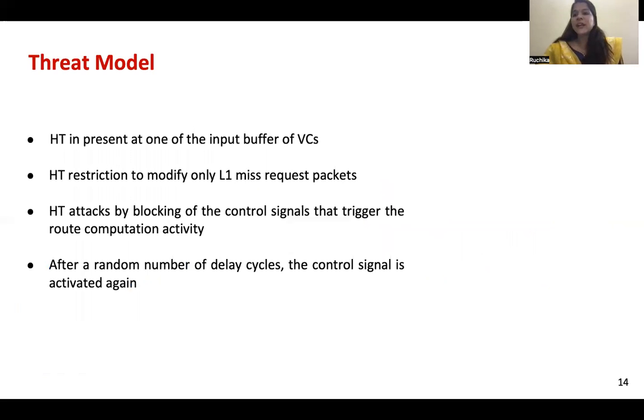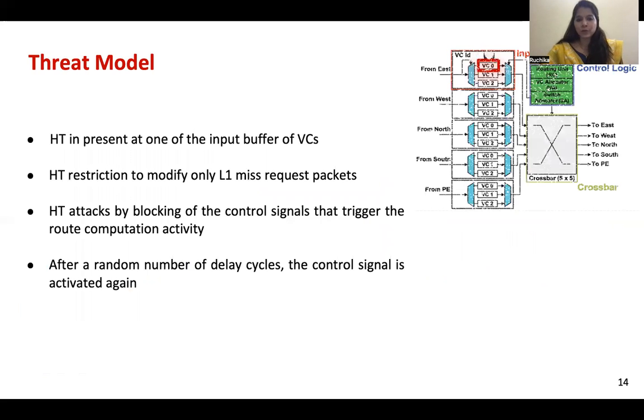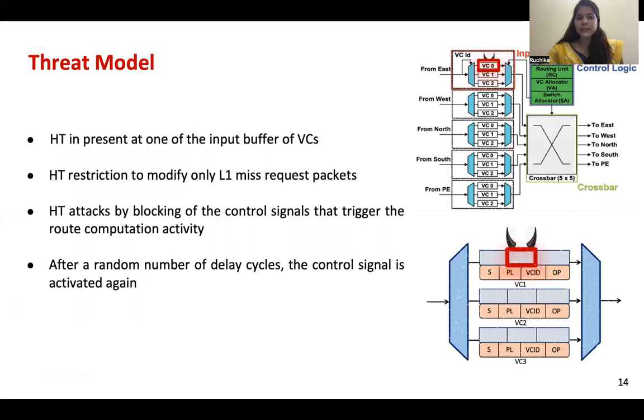So in this work, we are proposing one such hardware Trojan, which we call a delay Trojan, where we consider the Trojan to be present in one of the input buffers of virtual channels, creating a delay effect on L1 miss request packets.